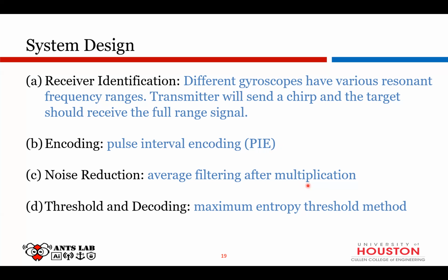And in this paper, they also mentioned the noise induced by the transceiver movement. If the scale is large, they use an adaptive threshold. But if the scale is small, it can be regarded as noise, and this noise can still be separated after some domain transfer or using some empirical mode decomposition. Anyway, it's separable, so it can be removed sufficiently from the useful signal.